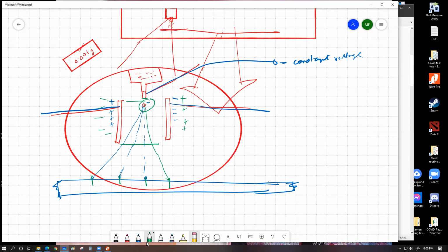Also, by controlling the voltage on these two plates, you can pinpoint exactly where on the page this ink droplet is going to drop. And that comes through a lot of constraints. Keeping the ink droplet mass same for every droplet, keeping the charge of the ink droplet same for every droplet, and controlling the charge on these two opposite plates very precisely, so that the ink droplet is bent by a very specific amount and ultimately drops on the page at a very specific location.